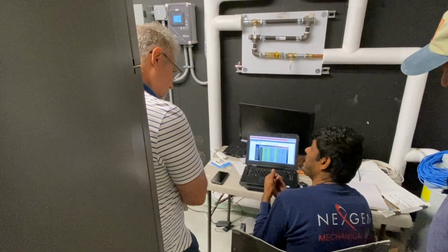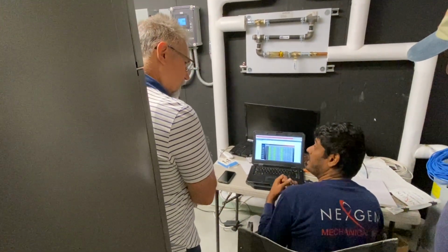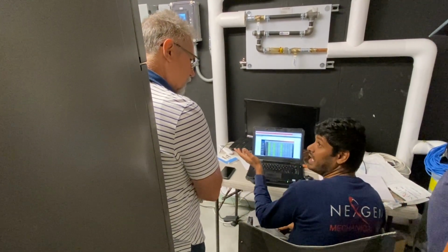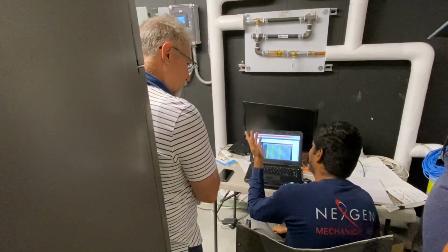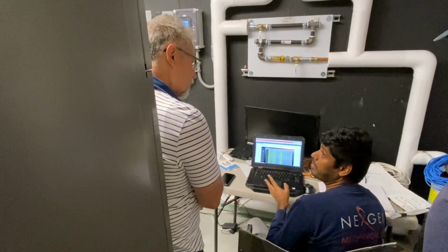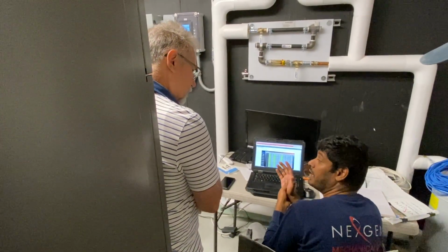And let's say when I'm in a heat mode, it is going to drive the valve open and radiate the heat. So all the valves above 1 GPM are modulating. They're going to modulate to open from 0 to 100%.